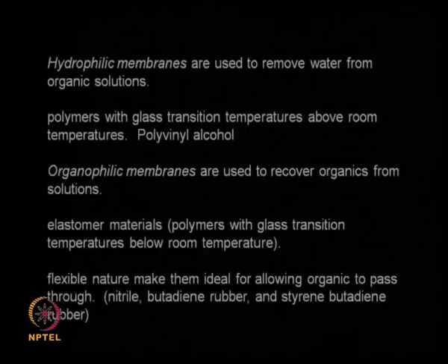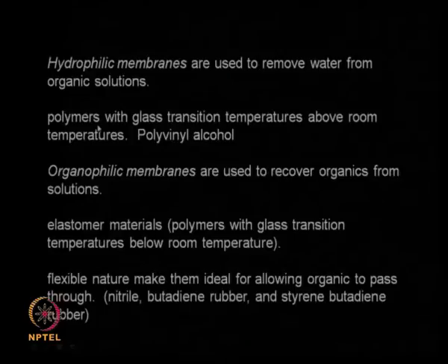So I am interested in only removing that water. So obviously you have to have membranes which are water loving or hydrophilic. So polyvinyl alcohol type of membrane, okay, polyvinyl acetate and so on. So these membranes should have glass transition temperatures above room temperature.